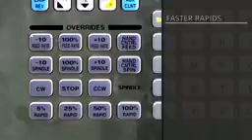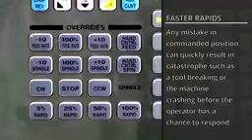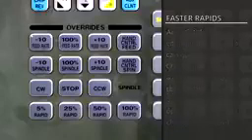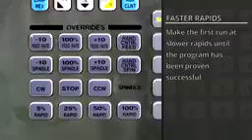With 50 and 100% rapids, any mistake in commanded position can quickly result in catastrophe, such as a tool breaking or the machine crashing, before the operator even has a chance to respond. These sorts of mistakes are very costly, but preventable by making the first run at slower rapids until the program has been proven successful.